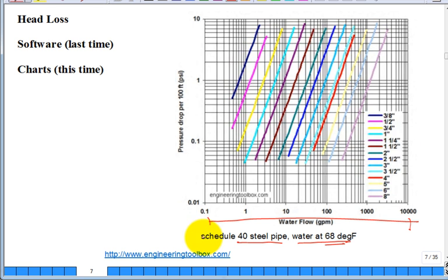And they're saying if you pick to do it with the 1-inch pipe or a 2-inch pipe, here is the 2-inch right there, right? Where's the 1-inch? There's the 1-inch right there. Look how easy it is if I want to push 10 GPM through a 2-inch pipe. I'm only going to have a friction loss of 0.1 head loss per 100 foot. Sometimes they'll quote it in foot per 100 foot. Sometimes they'll quote it PSI per 100 foot. Here this is PSI per 100 foot, so 0.1 PSI.